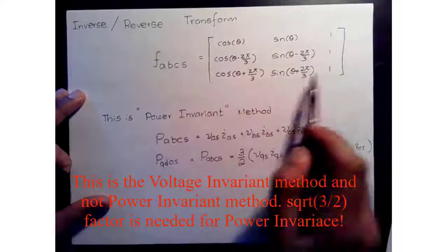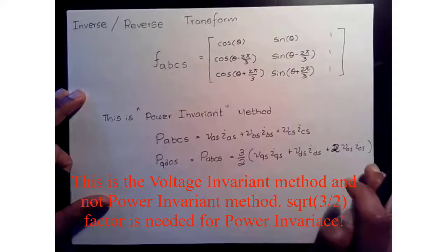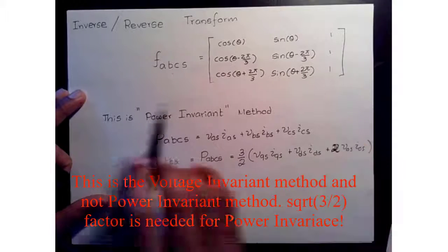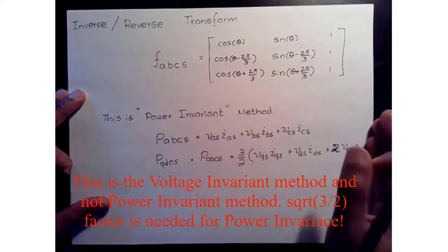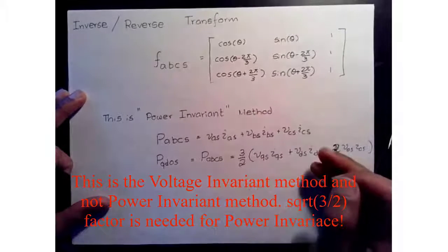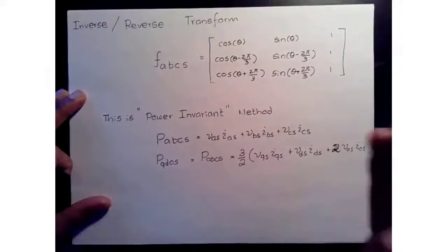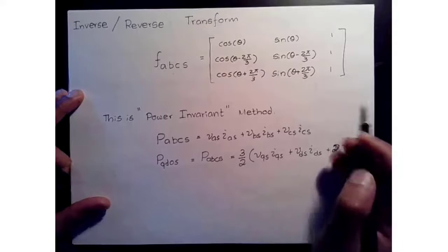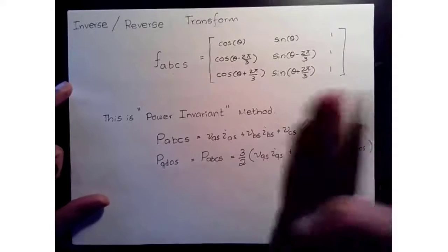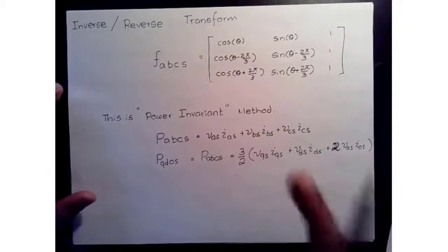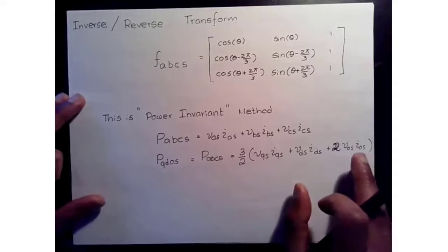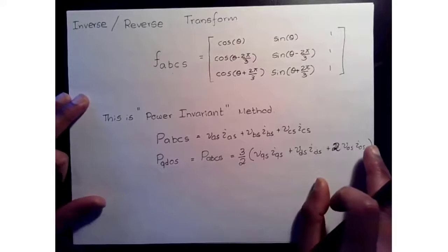So this is that inverse transform that you can use. All right. And if you want to try, I would recommend, just generate 3 sine waves in MATLAB, in Simulink, apply this transformation with the position, and you'll see that your measurements will look DC. They'll look like steady. And you can even play with your frequency. You can change it to slightly different, a lot more different, reverse. You'll see different phenomena happening when you change your frequency from that synchronous frequency.